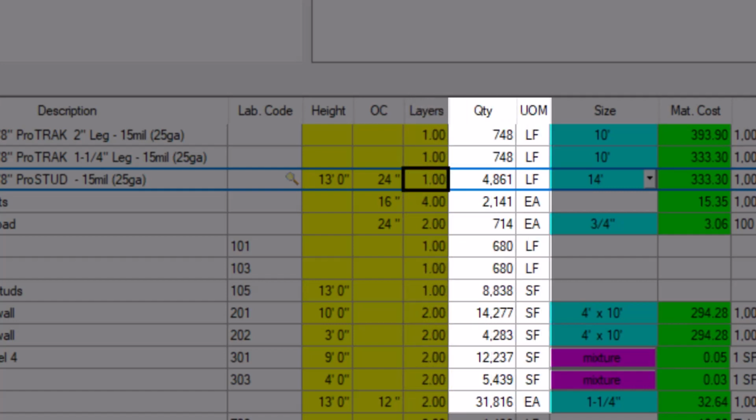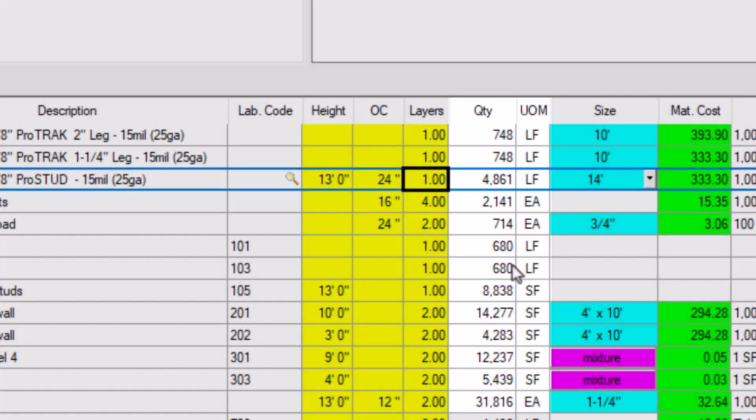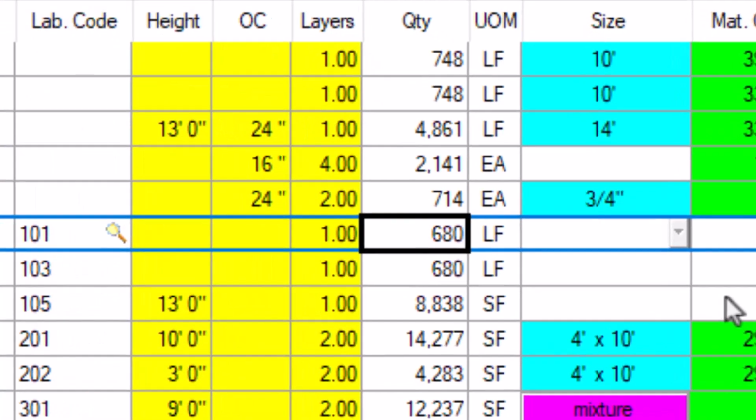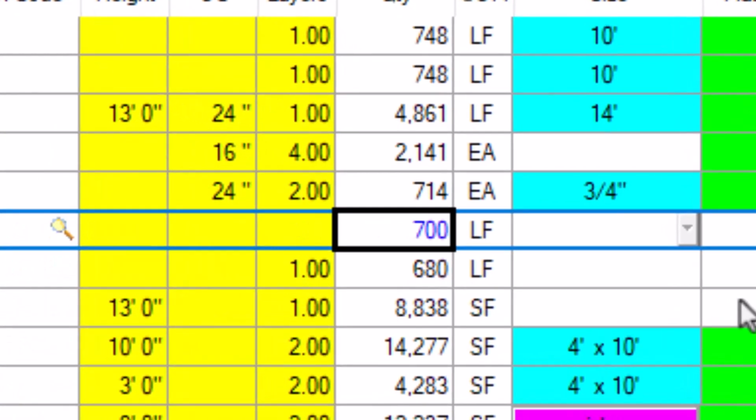The quantity and unit of measure fields are the results of all of your calculations. The quantity may also include additional waste. The amount of waste isn't visible on the condition detail window. However, it can be seen and edited on the Materials tab. In most cases, you shouldn't change the quantity directly, but it can be done if necessary or even required on Enter Direct Quantity items. Manually changing the quantity overrides any calculations and wipes out any variables. Manually entered quantities appear in blue.